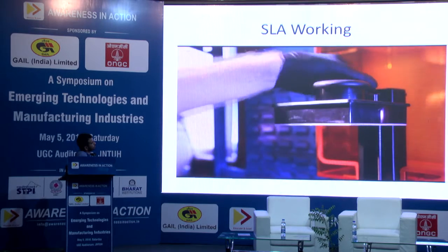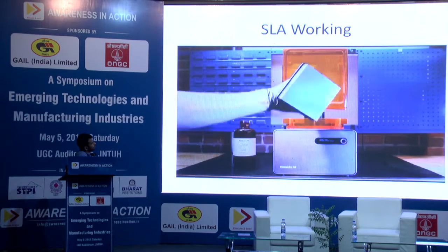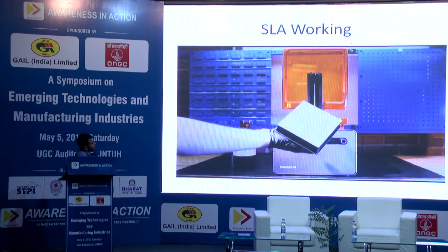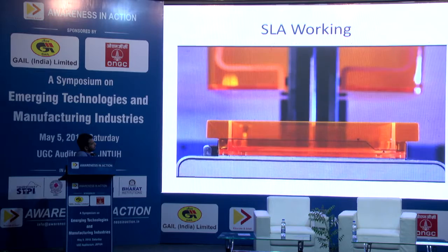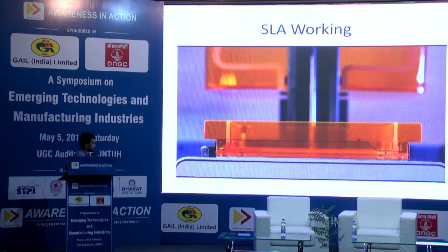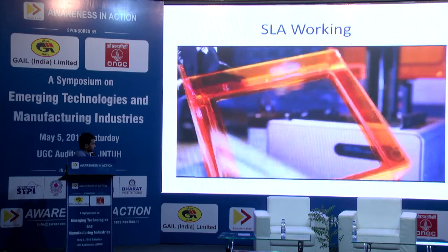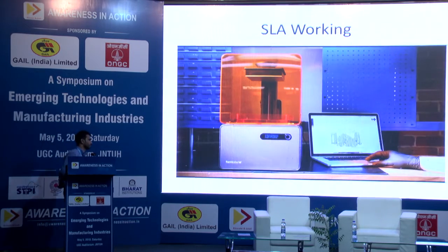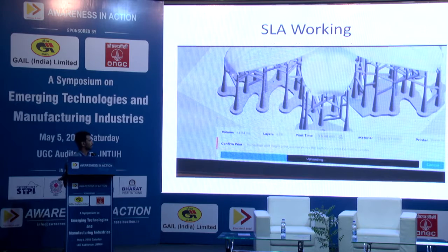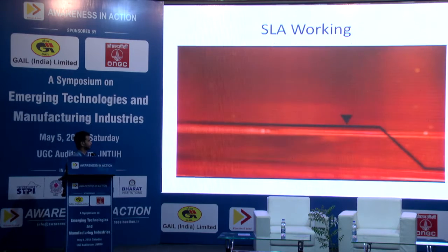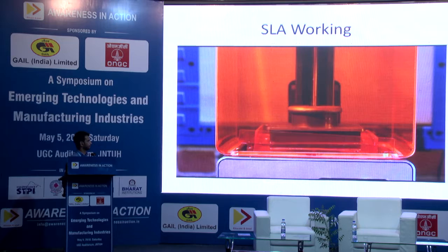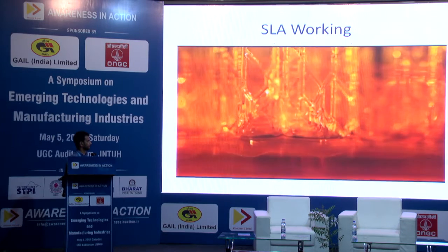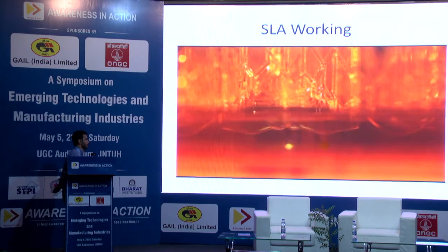When we open up the light-blocking cover, we can see a build platform inside. This metal plate is where the parts are made. Underneath the build platform is a resin tank. This clear window gives the ultraviolet laser a path to cure the resin. To start a print, we'll upload a file and fill up the resin tank to the indicator line. You can see the laser passing back and forth inside, hardening the liquid plastic.